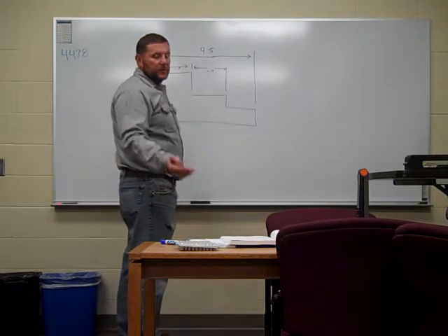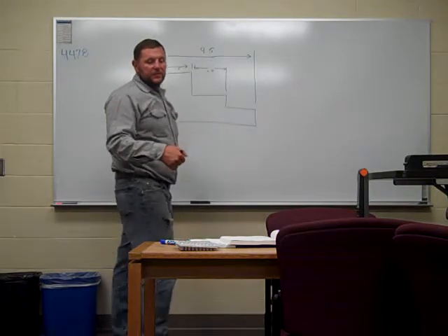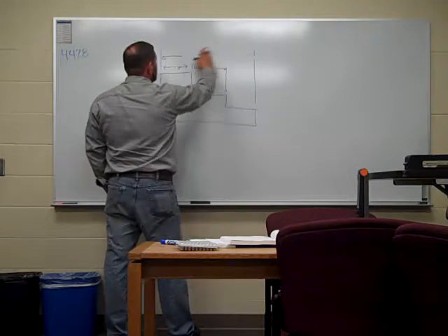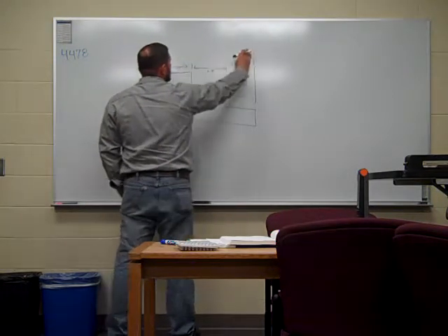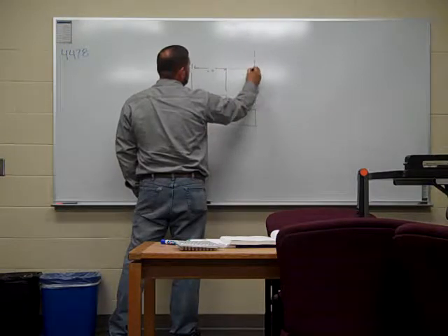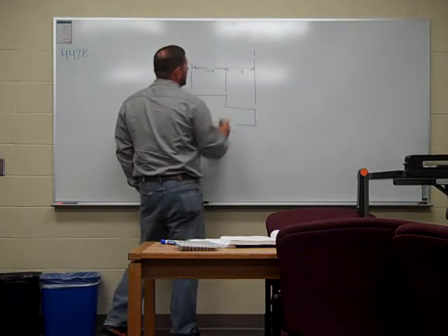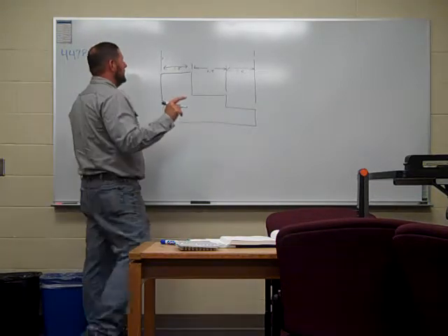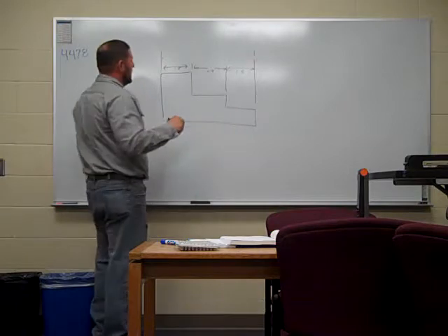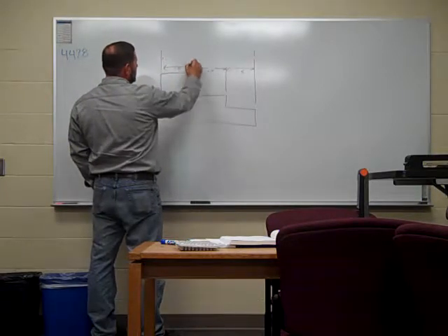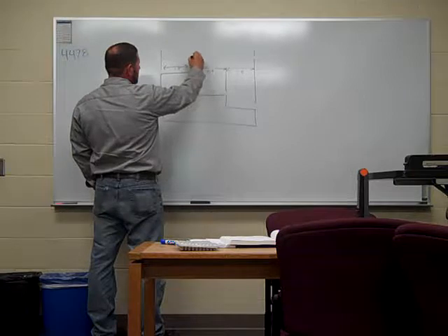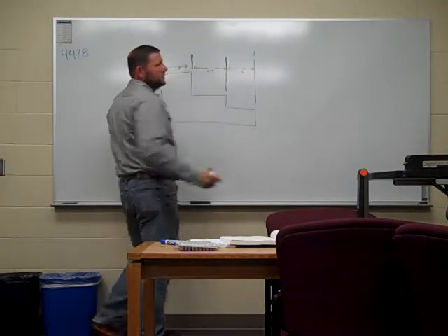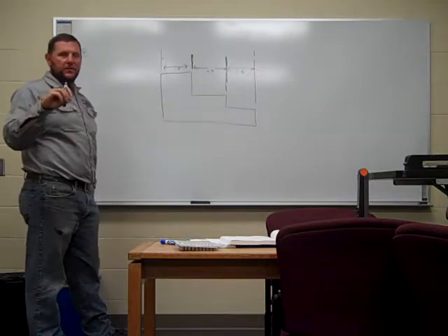So, a couple different ways. As you go to the model below it, it's giving you the chain dimensioning of this. They don't give you the overall length, so then they give you another dimension here, 1.5. Now be careful with that chain dimensioning, main reason being because you can have error. If I was going to measure this part out, I would not measure from here to here, and then put my tape measure at this point right here and measure out another 1.5, because you're going to have error in where you place that tape measure.